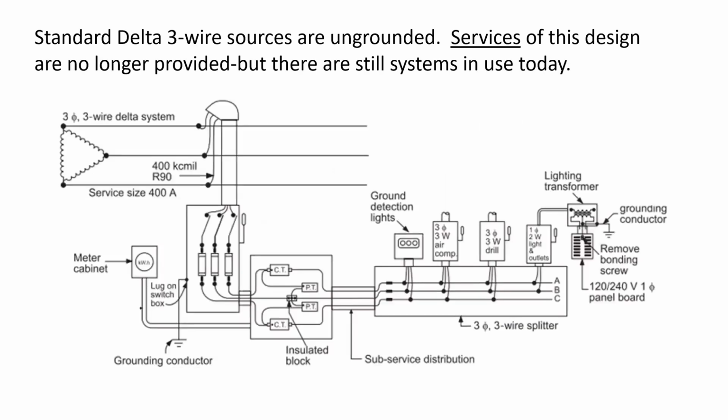Standard delta three-wire sources are ungrounded. Now, services of this design are no longer provided, but there are still some systems in use today. In this example, you can see that there are only three conductors coming in, and it's off of a system that is ungrounded.